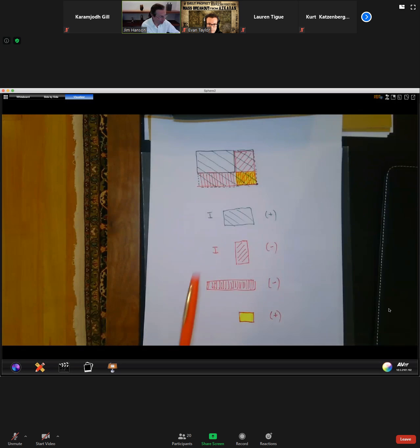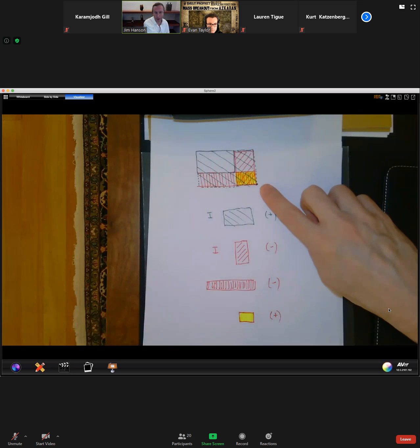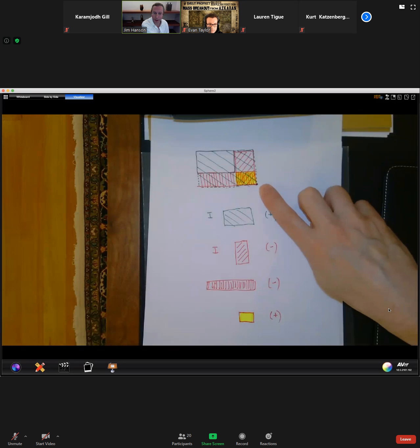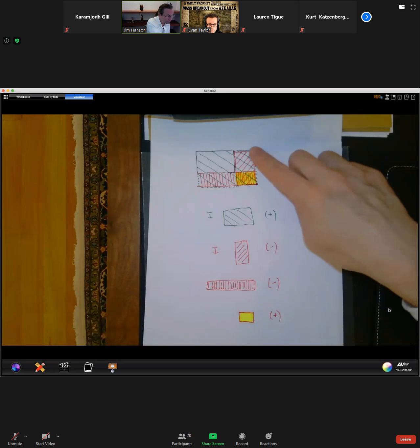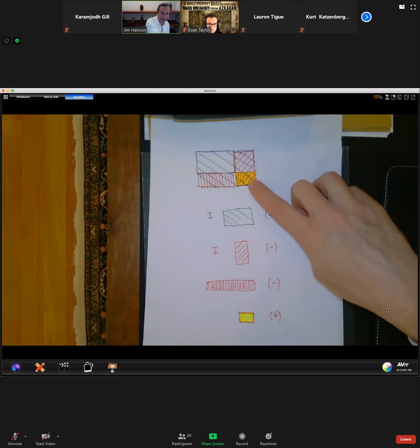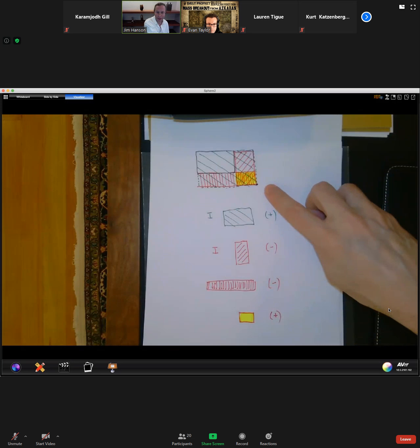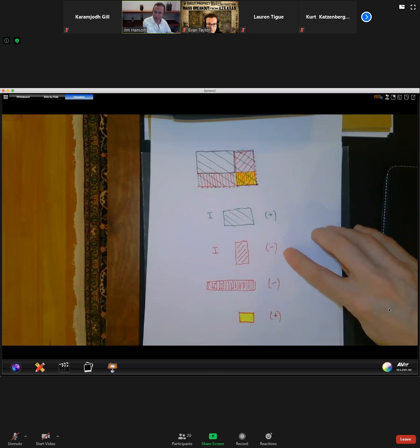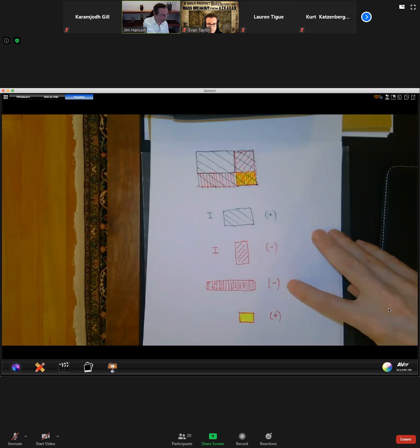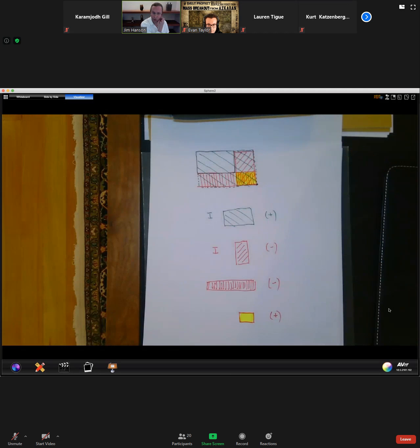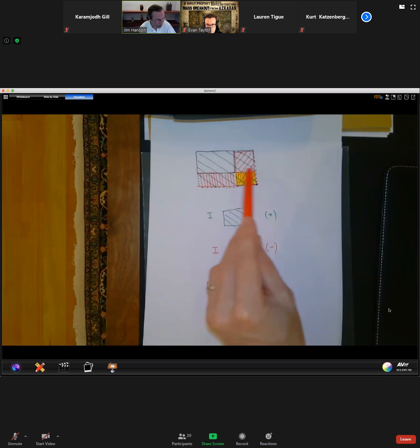So you'd have the big green area, the whole thing. Go to the table, you're at the corner of a rectangular loaded area, check, it's a valid use of the table. Next up, you remove this vertical rectangle. You're fine. Using the chart, you're at the corner of a rectangular loaded area. That's minus because you're taking that area out. Similarly, the long, shallow rectangle with vertical stripes on it is going to be minus. Now, though, this yellow area you've taken out twice, you actually have to add that in.